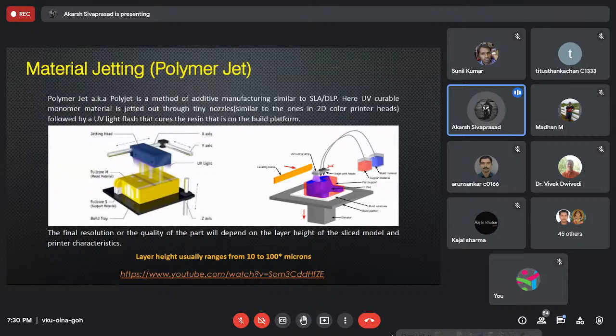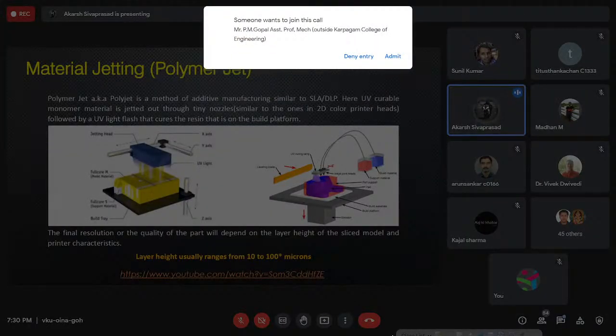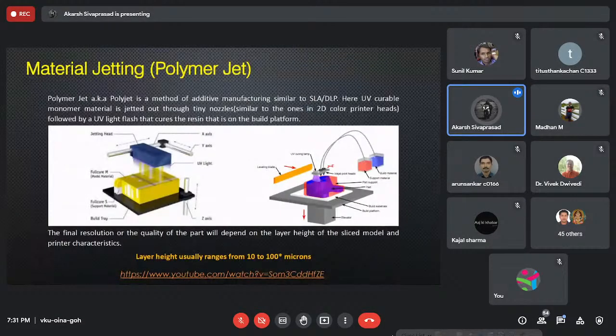It's also a drawback at the same time because you end up wasting more material. If you want to print something like an umbrella, upright, then you need a ton of supports under the bell, more than the entire material that you're going to use. So the waste is really high on this. This technology can go down to 10 microns to 100 microns depending on the material that you pick and use. It's relatively faster and not that messy compared to SLA and DLP.